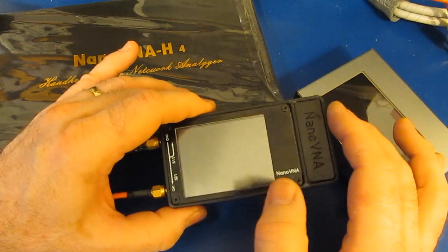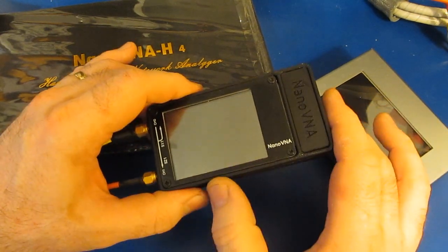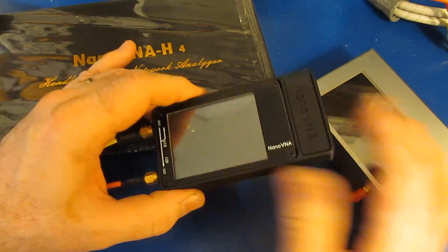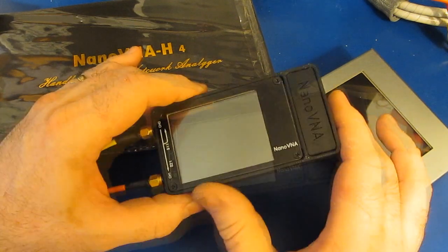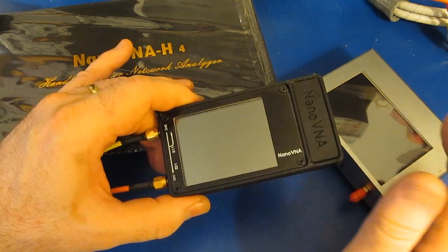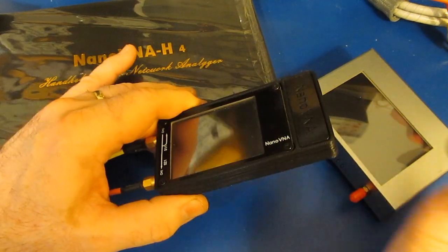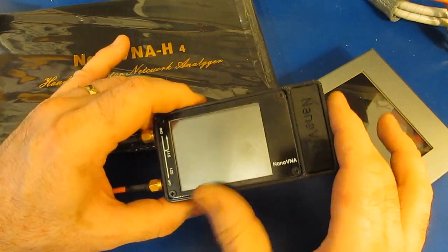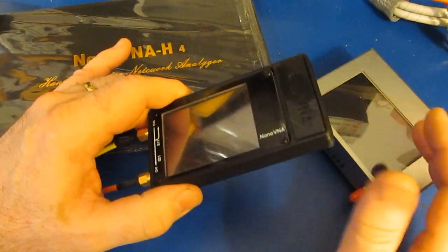Another problem that you run into is the inductance of a lot of components is going to go up at higher frequencies. So if we're trying to measure low impedance, we may have to do that at lower frequencies. We'd also like a network analyzer with very low noise and also a very wide dynamic range. And the reason for that is typically with a PDN, we're trying to measure very low impedances. Most of your PDNs are not going to be 50 ohms.